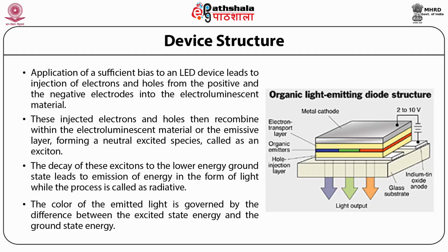The key in this device is to maximize the recombination of charge carriers in the emissive layer, and hence it is important to design and tailor the structure of the organic layers as well as appropriately choose the anode and cathode, maximizing the light output from the OLED device.